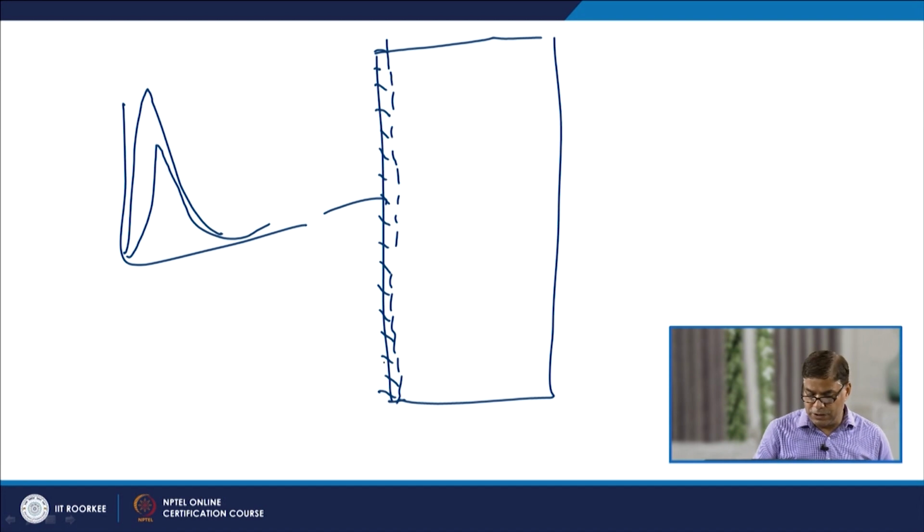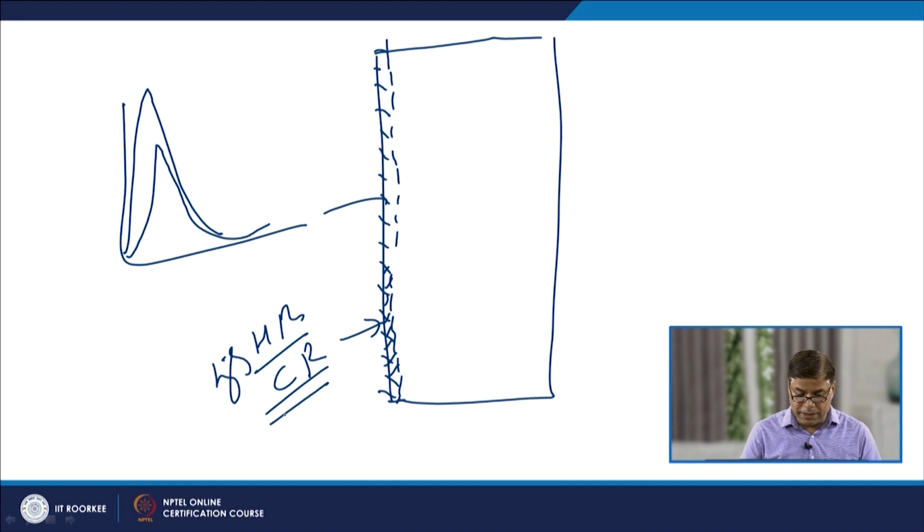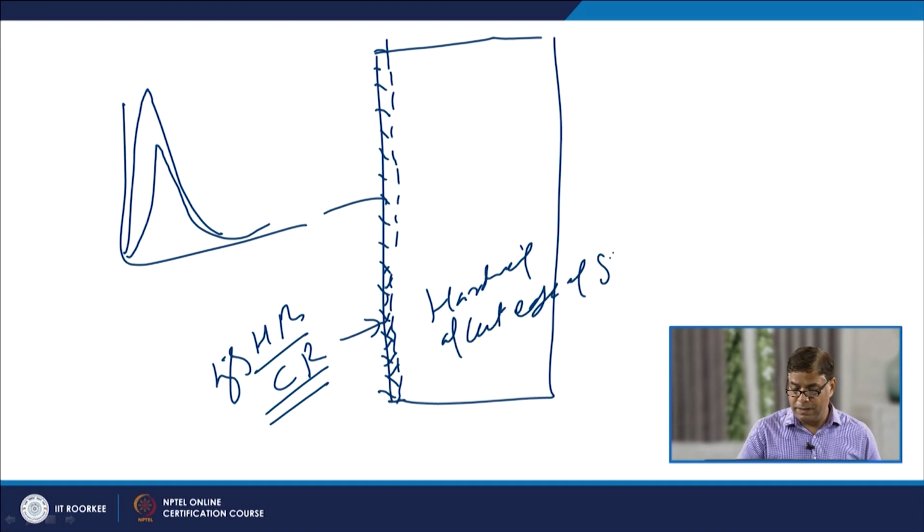So, the zone very next to the cut edge experiences a very high heating rate and likewise a high cooling rate. These cooling rate conditions are high enough to harden the cut edge of the steel.